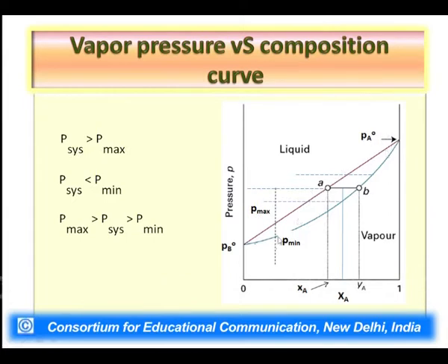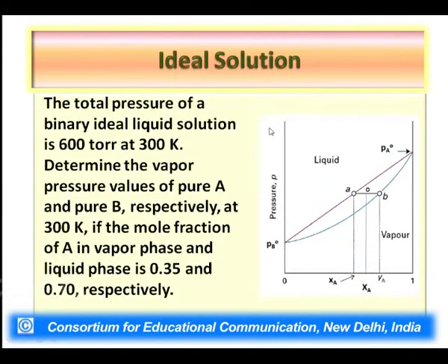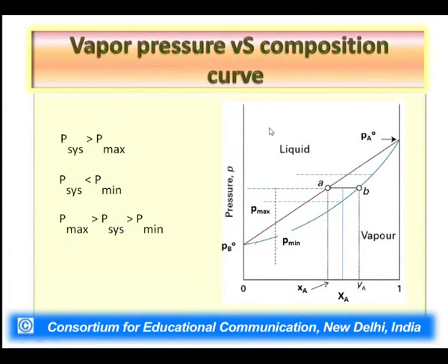All the points above the liquidus curve, or the purple curve, represent a big area, in which there are a large number of points. This area is the locus of an infinite number of points, where each point in this area represents a particular state of the system.